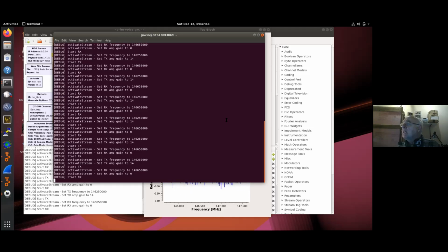Sort of tangential to that, a lot of the problems I had with the power amp itself, because it was my first project, is to make sure your input and output are 50 ohms all the time, because otherwise the power amp chip will oscillate or self-destruct. And you have to do that even when the relay contacts, or whatever switching mechanism you have, is active, so you have to control the bias to the power amp and so on. So that was another lesson learned.